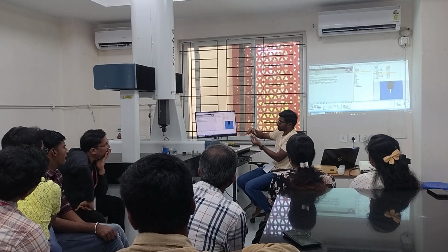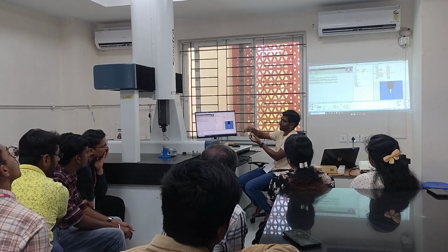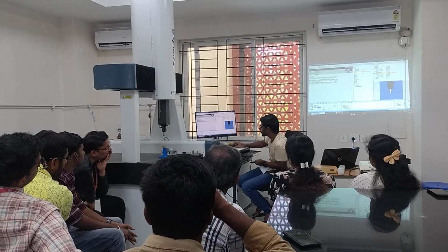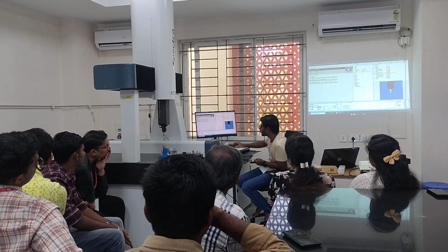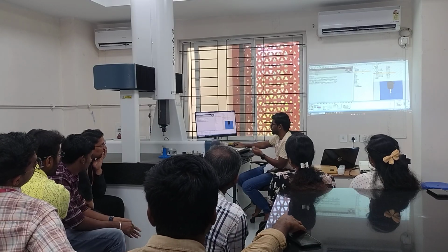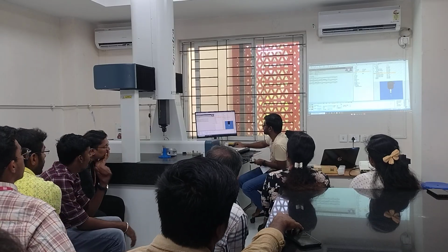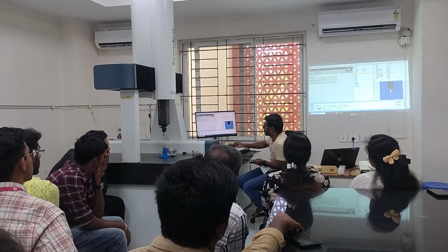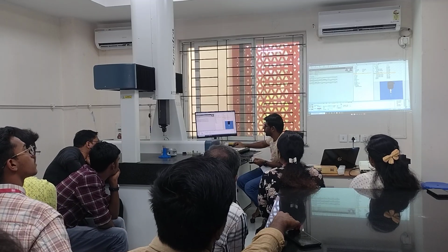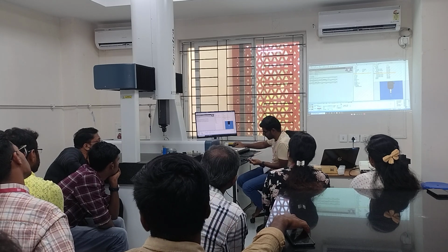What I have measured: flatness of this, angle of this, distance between this, and let me see the circularity of this. I'll go to measure the radius, or the diameter. Diameter of what? Diameter of the circle. I'll drag the circle here, and then I see it here as 24.930. So that is what it is showing us.